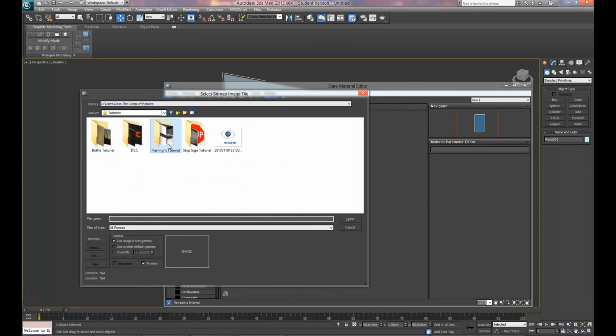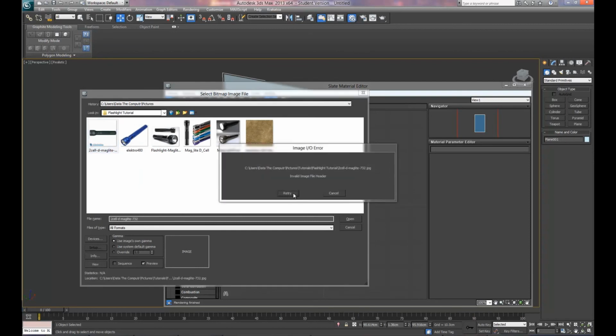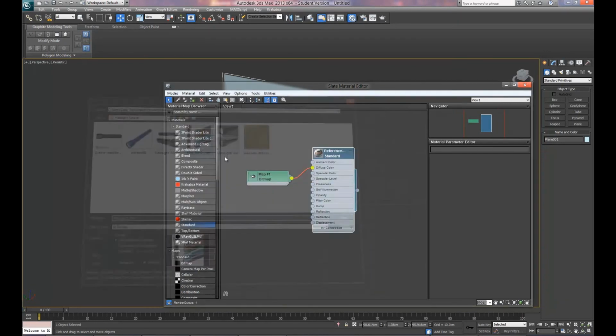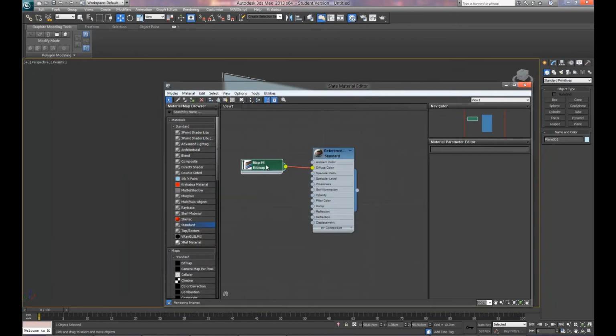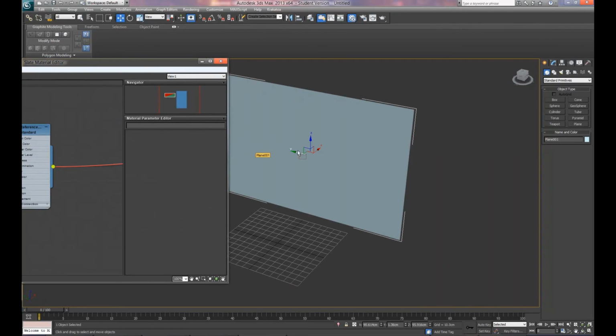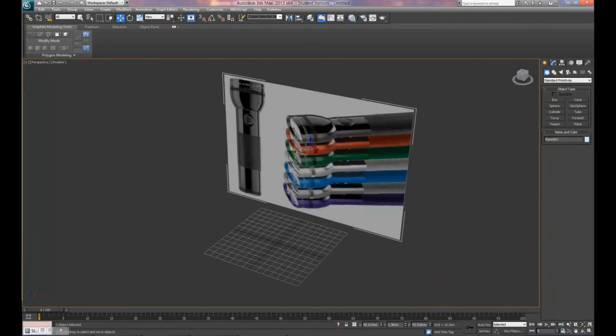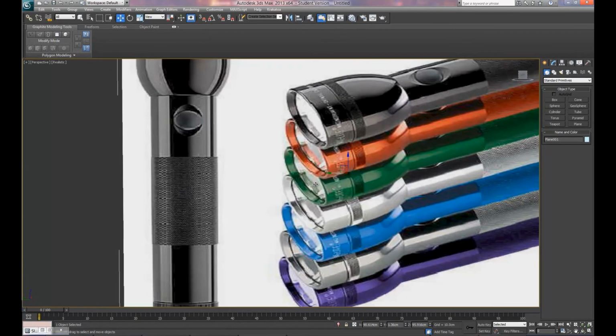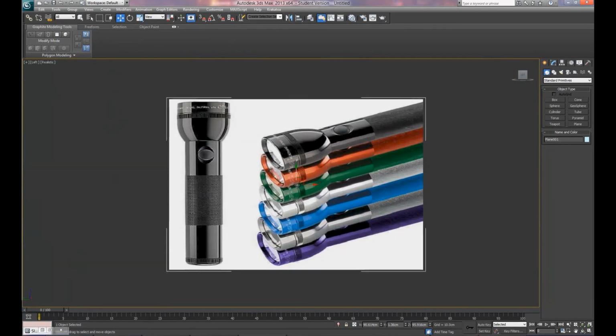your project files, and for this tutorial we're going to use this file right here, and it will be included in your project files, which are in the description, and will include the texture for the ground when we render it out, as well as all the reference images you need to complete your model. So with this selected and all this set up, click over here to show shaded material in viewport, and then drag it out. And as you can see, we now have a reference image.